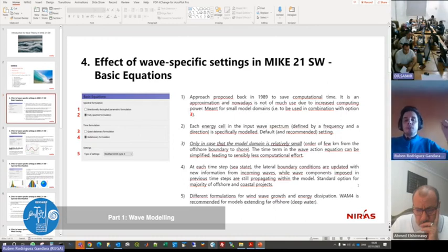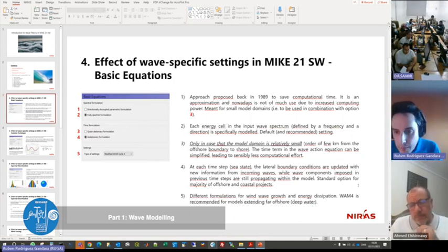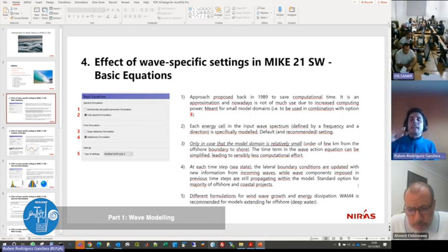Let's say that now you compute, you have a distance of 70 kilometers, and the velocity of the smallest wave is going to be, I don't know, 1 meter per second. That will give you, for example, a ratio of 3.7 hours, which means that, okay, for the smallest wave that I'm going to model, it will take 3 hours or 3.5 to go from the boundary to the land. But the problem is that every hour, I will have to update the forcing conditions at the boundary.